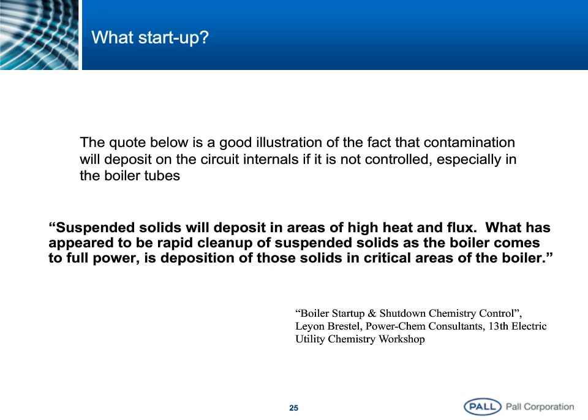So really, many times I've had conversations where people can show me a curve of particle contamination going down as they bring up the plant to full power. And you can't deny that. The problem is, where is this contamination going? Because it's certainly not disappearing. So either you remove it with mechanical ways, like a filter in our case, or something else is picking those up. And that something else is very often the boiler. And that's where a lot of the problems will start.